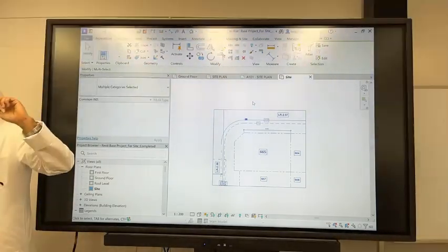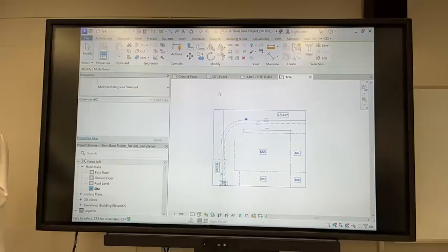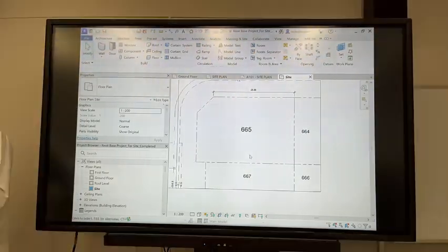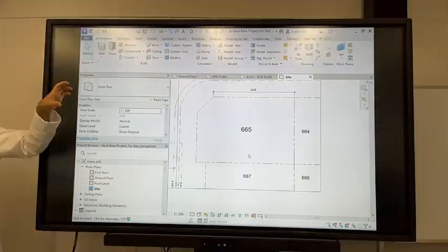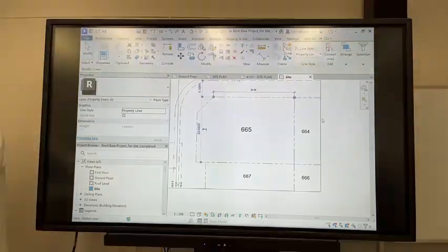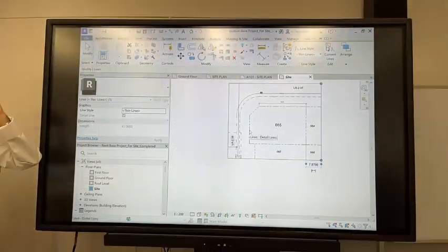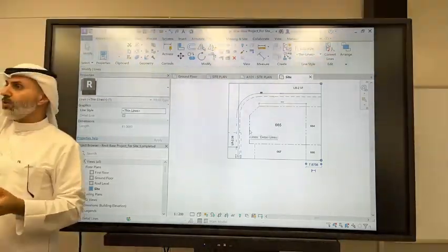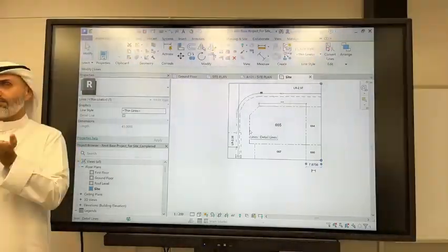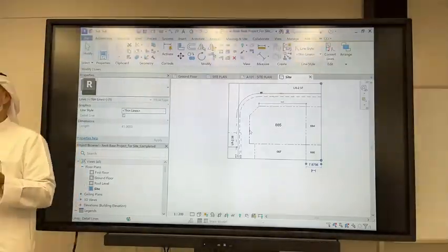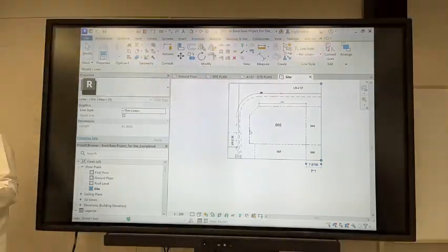Hey, before you paste it, open the other file. And you'll notice it has the border model property. So the file that has the building, turn off the site in it, you will find only the property lines, right? And the frame. Right? Erase them. If you don't erase them, you're going to take them from the old file to the new one, and then you're going to have 2 lines of each. Okay? So erase them in the new file. You already did that? So find them and erase them, so they're not double lines.